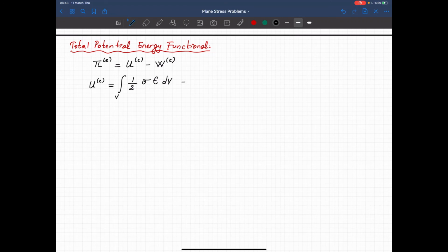So for the volume, since we simplified it, I can write the following: integral over the surface, 1/2. Instead of stress, I can write E, multiplied with the strain, so strain multiplied with E multiplied with strain. t times dS will give me the d volume.